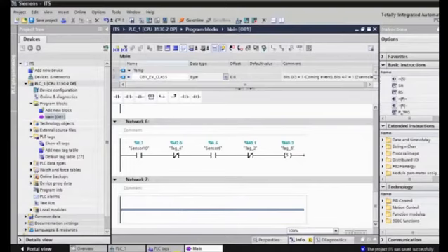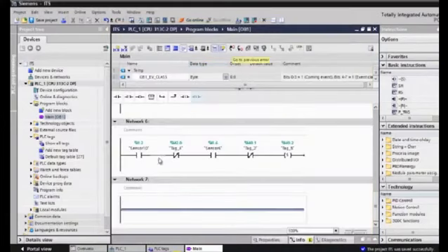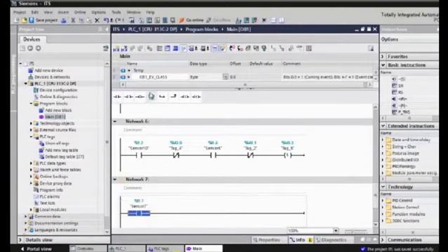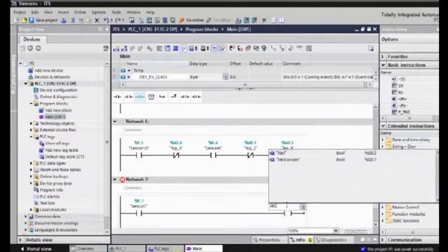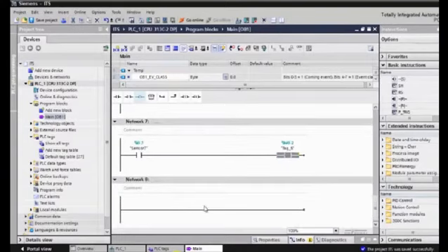But where should this elevator be stopped? At sensor number 7. So we are going to use sensor 7 to reset this marker, which is going to bring the elevator up. This marker is used to bring the elevator up.